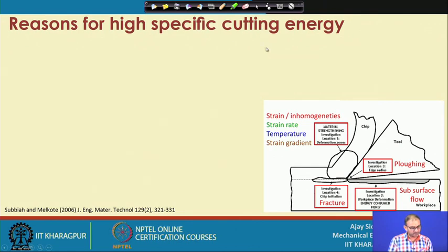Right. So, what are the different regions? We have seen many of them, so let us summarize. We understood this particular diagram when we started the size effect. Here we have seen that there are 4 different locations through which we can understand the micromechanics much better compared to conventional machining processes. First, strengthening due to the lack of defects, which we saw in the previous slide. We are not able to find enough defects at the small scale or small volume of the material, and because of that the material becomes an ideal material and you are not able to penetrate the tool very easily.